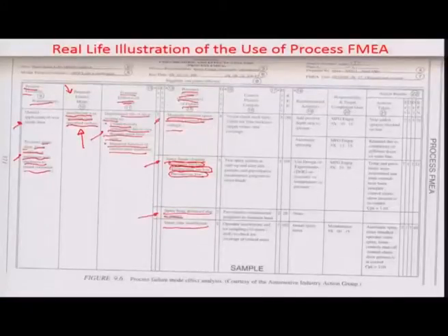So sometimes, because of the untrained operator and his inability to keep up with the flow of the production process, he might find the time between many vehicles coming sequentially to be insufficient to coat the whole vehicle with a certain wax layer. On one hand, the line is balanced for a skilled operator, and if you put an unskilled operator, these problems are going to happen. So the quality engineer again tries to decide on the occurrence levels which lead to this failure mode through the various mechanisms.